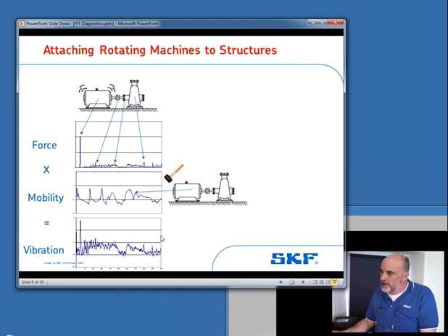What's next? Right, so we're going to be looking at a signature very shortly. And we have to remember that there are two contributory factors to that signature. There are the forces, as we've said. So we've got the running speed of the motor. We expect that to be the biggest peak in our spectrum because that's the highest force. If we're dealing with flexible couplings, we might have 4 bolts in our flexible coupling. Therefore, we expect to see a high 4 times running speed pop up in the spectrum. And so it goes on. We might have blade pass frequencies and the like.